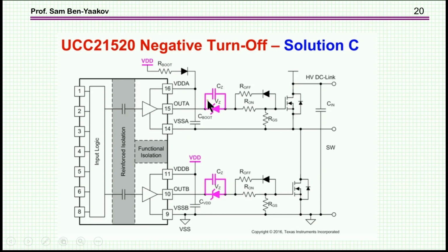This is the Zener across this coupling capacitor, and we have seen this before. And here the only difference is we see here the on resistor, the off resistor. This is just a bleeding resistor, because you have a capacitor here, the gate is capacitance, so you need some sort of leeway for, say, leakage current, etc. So this is just a bleeding resistor, and here it's shown for the upper and lower transistor, the same thing.